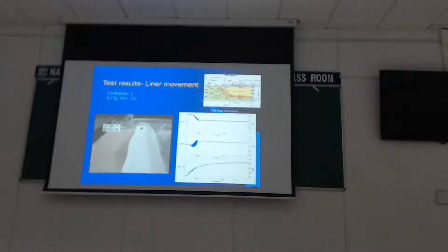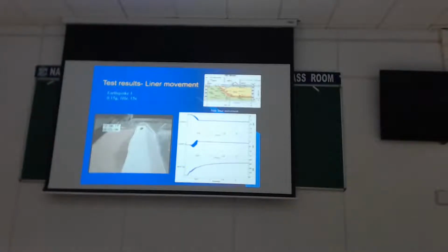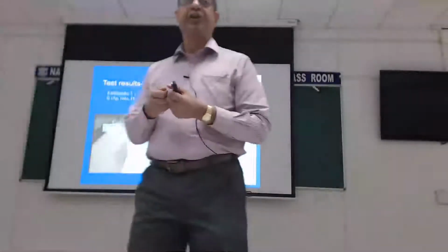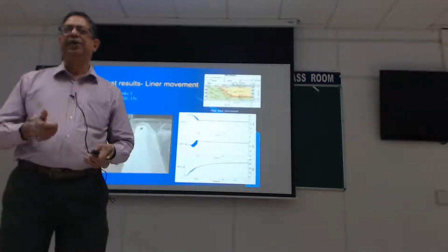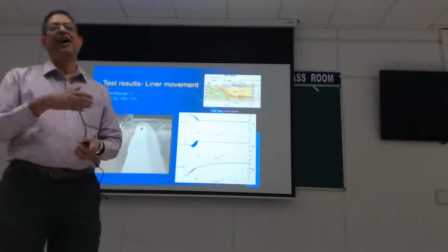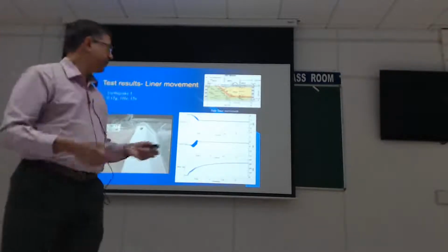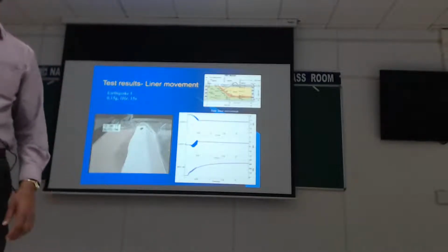So, for a complicated problem like this, using centrifuge testing, we were able to understand how the lining forces have changed during shaking. And one of the biggest things that came out of this research was that every time there's an earthquake, you get extra tension in the geomembrane, and that does not go away. It stays. So earthquake after earthquake, we kept applying, and you could see the residual tension going up and up and up. And there's a very nice paper about this in Geotextiles and Geomembranes, I believe. If you like, you can have a look.